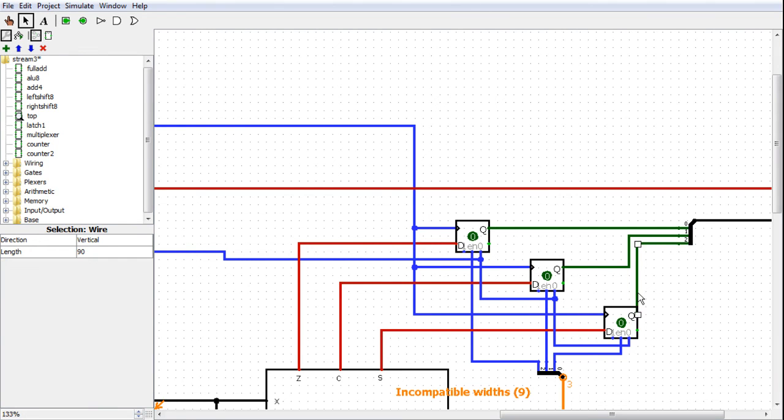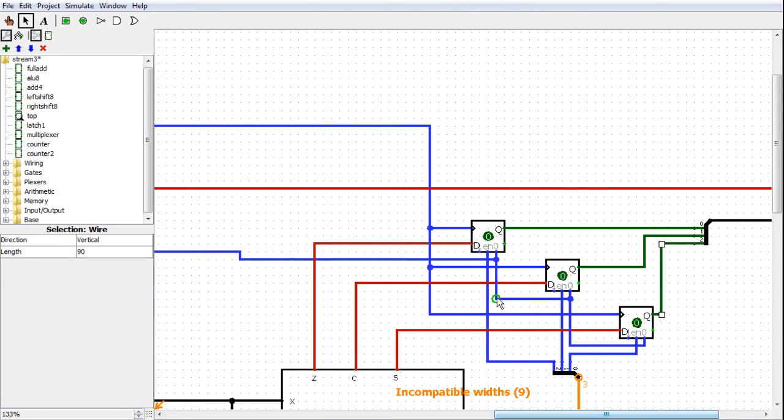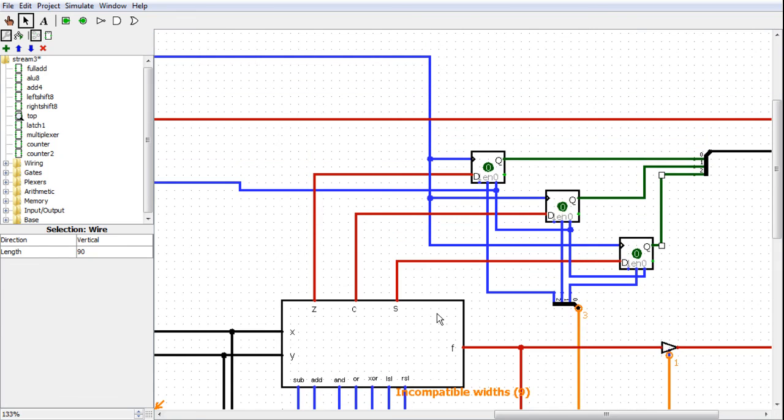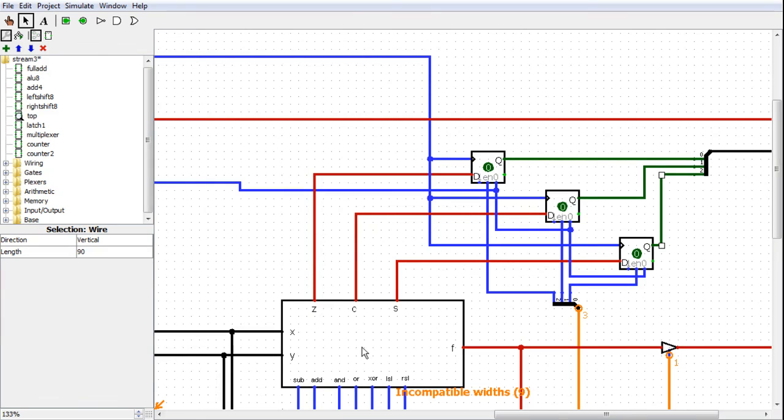Probably because it's so small that it looks like it's labeled CT. The one that's coming down. No, further to the left? Yep. This? I don't know. I think it's fine though. Yeah, that's clock. This is a clock on the top. These aren't toggles. These are just data flip-flops. So they just take the values in from the status bits out of the ALU. All right, good. We have settled it.